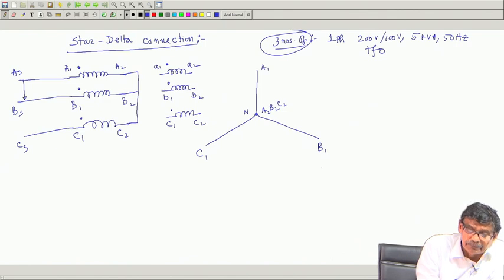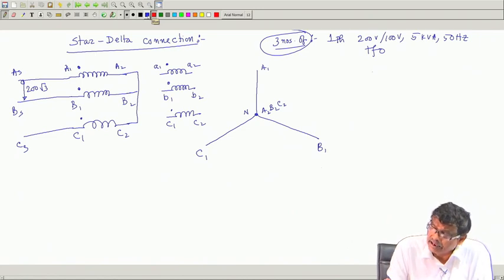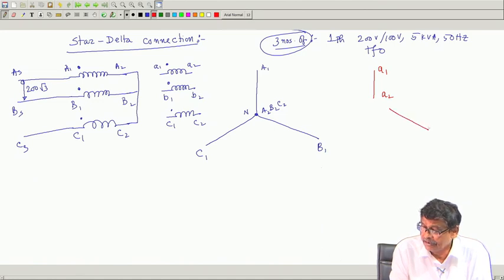because let us presume that I have applied 200 root 3 here. Now, on the secondary, as I told you, the next step is they first keep them in isolation. You have these 3 phasors available with you, whose length is half of this length, and each one of them is parallel to their respective primary voltages. So, B1, B2 parallel to this line, and this line and this line are 120 degree apart. So, the angle between them is also 120 degree. Similarly, here parallel to C1, C2.